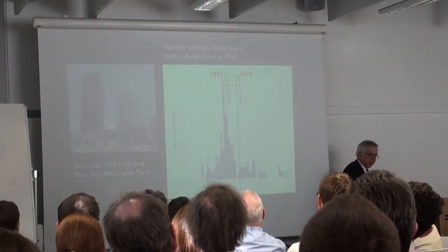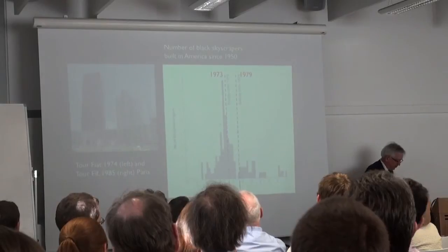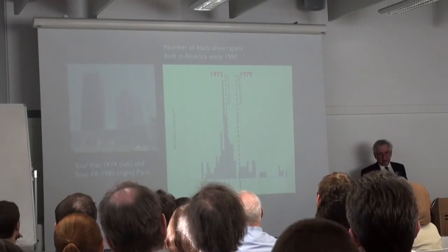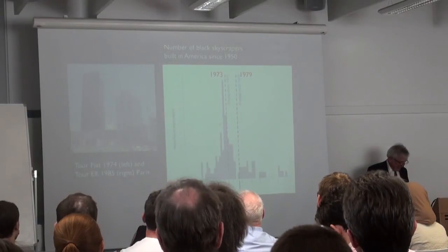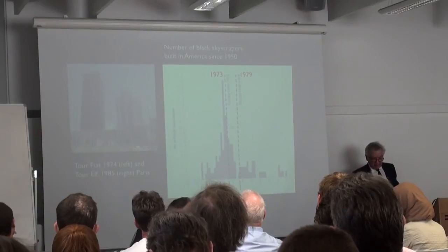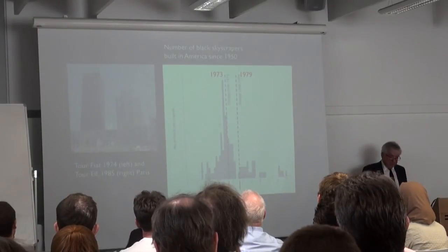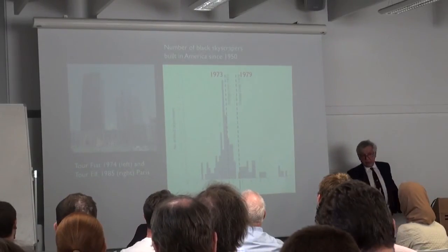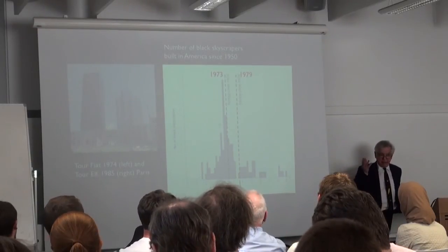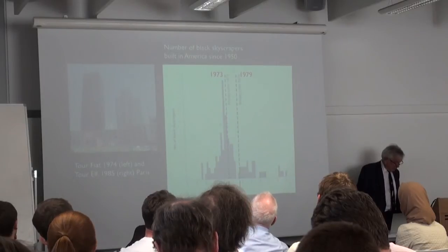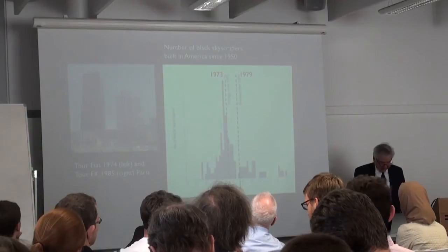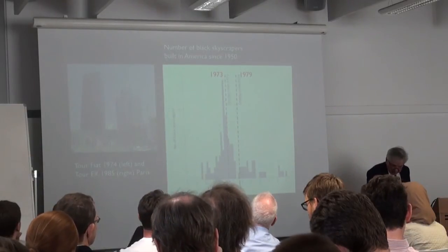There was a great reaction from the 70s, of course, in office design, with much research devoted to new kinds of glazing and new building codes, facade U values brought back down to 1.5, 1. Levels of artificial lighting which had been increased, despite these being glass buildings, were nevertheless brought back down again. But of course, many glass skyscrapers continue to be built worldwide. Some of us wonder why.